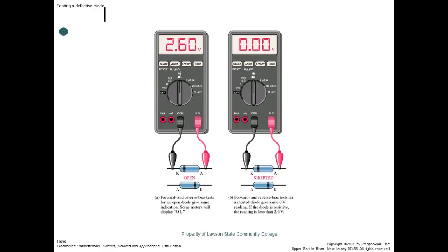So here they're showing a bad reading. We have the black lead on the cathode. By the way, cathode is abbreviated with a K. Y'all understand why? Because C is already used for capacitors. So here the cathode, now the anode, they're doing A, but K for cathode.